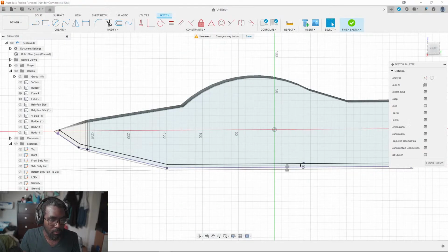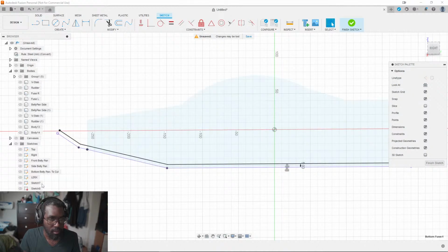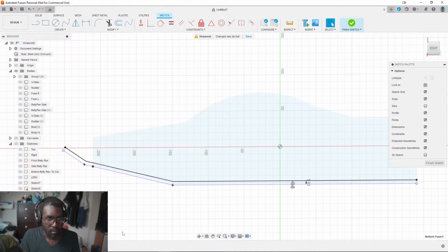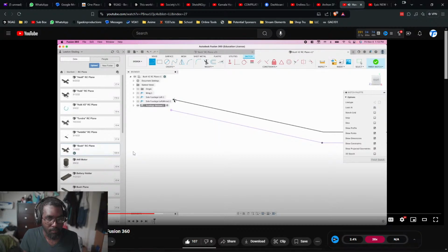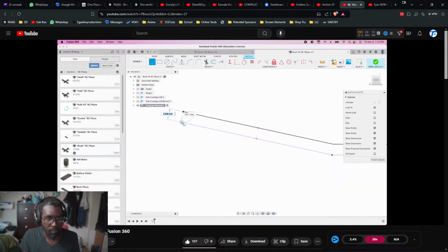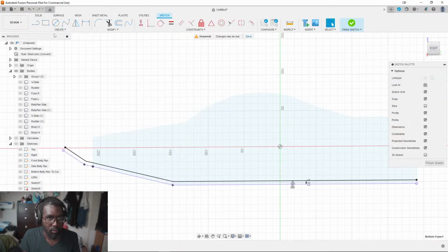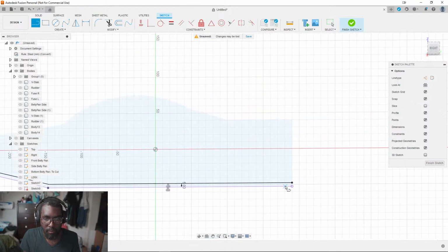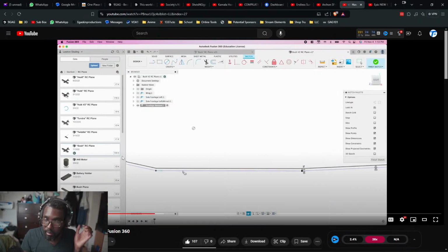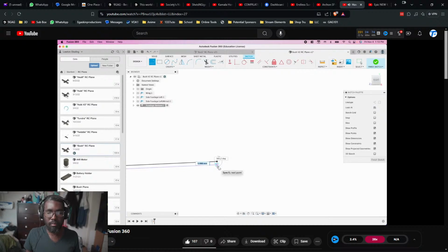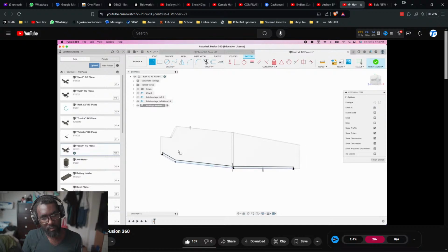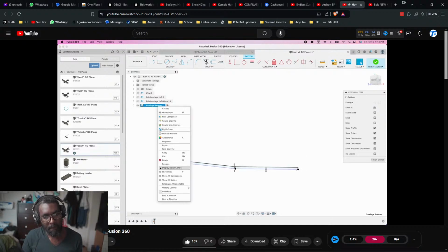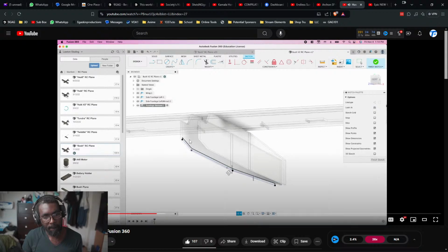Alright, fuse, bottom fuse, hit isolate, great. Yay! Close sketches, line tool, pop, pop, pop, pop. Edges. Cool, and then this is where it gets a little funky because, like I said, there's no good plane to actually extrude this along since it has to taper at the end.